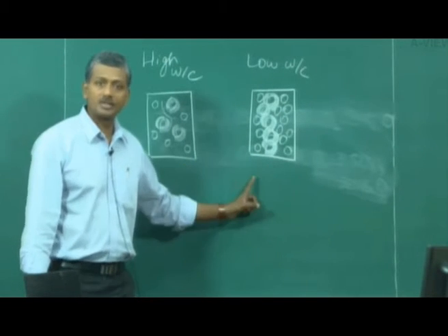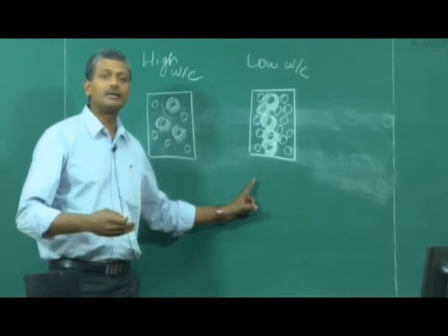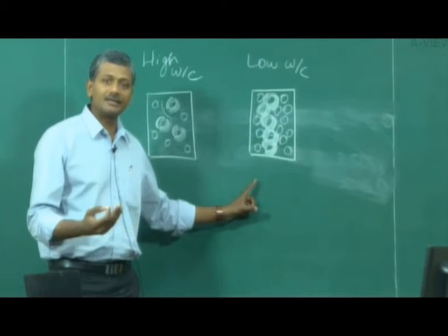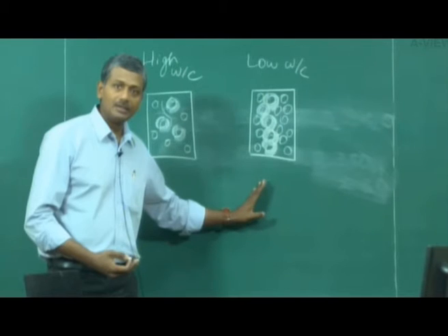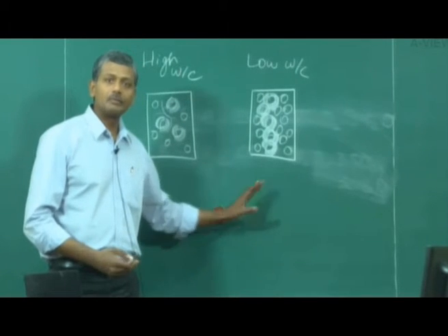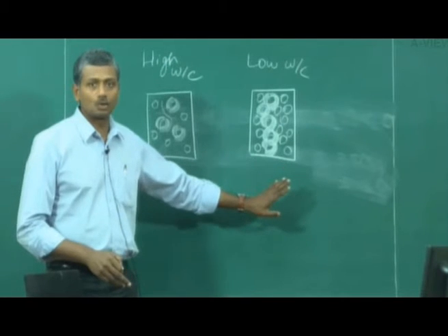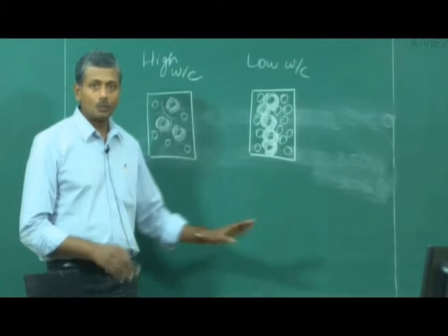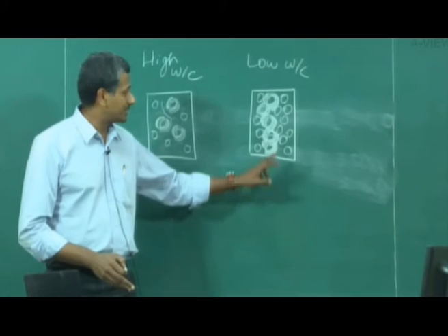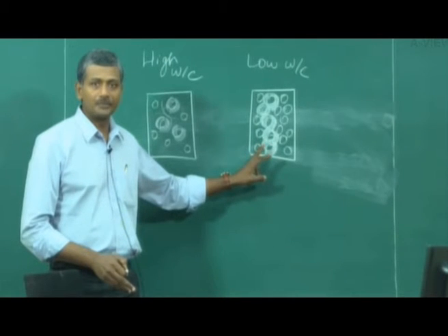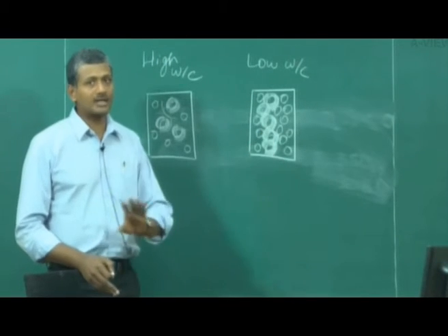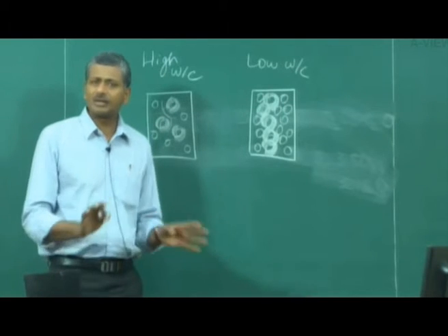So, in a low water cement ratio system, not only am I producing setting and strength gain happening much faster, but my overall filling up of the available porosity is much better in the case of the low water cement ratio system. Now one thing you should also understand is that when I do not have sufficient water in the system, my cement is also not going to get completely hydrated, but that is not really a problem.